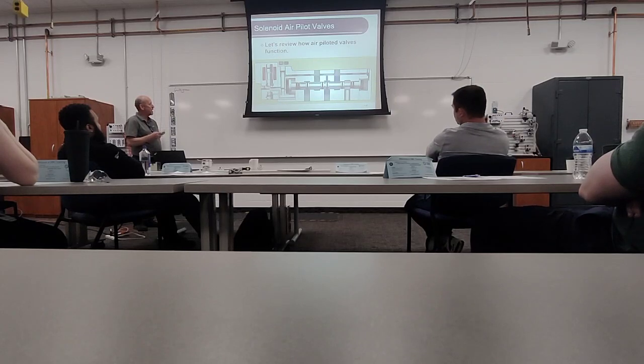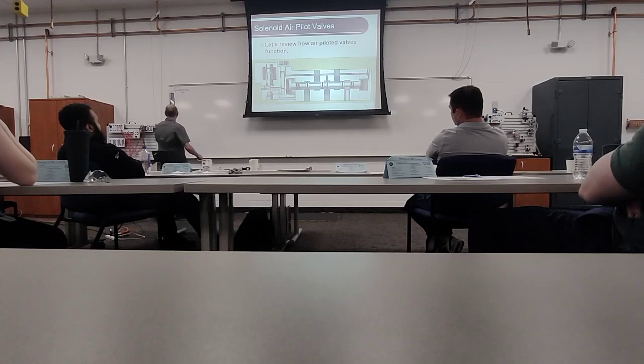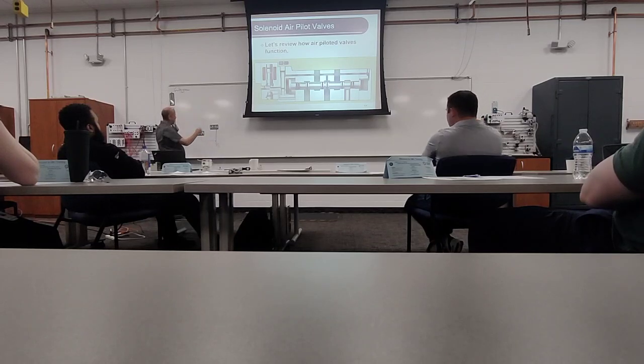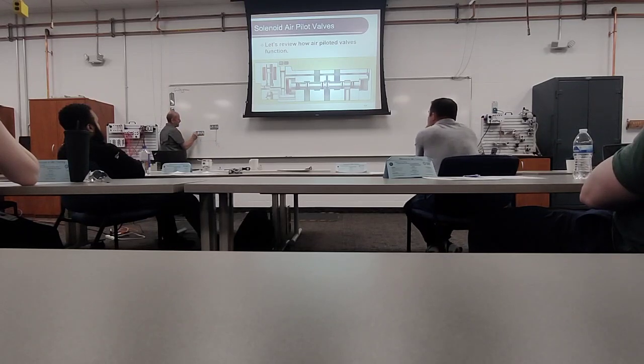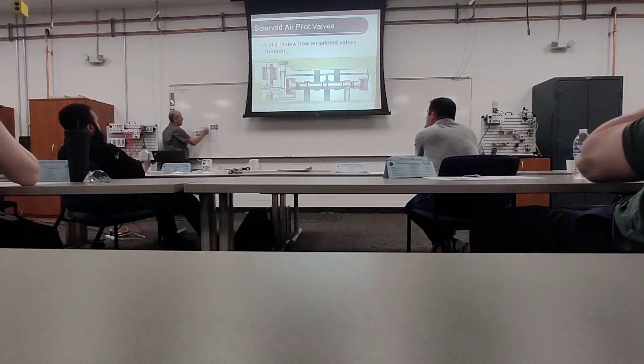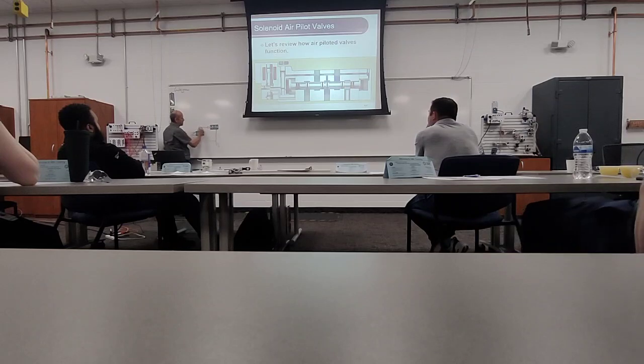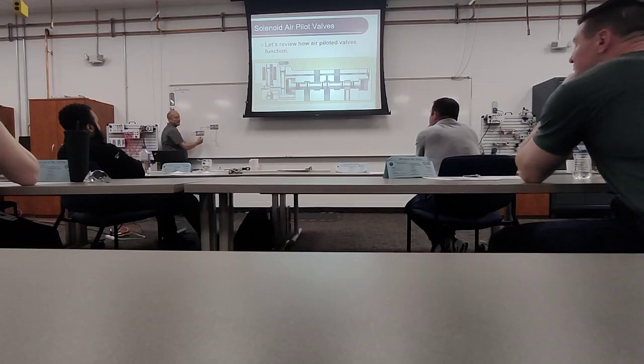This is the override, and then this is your solenoid valve. A solenoid valve is actually a 3-port valve. So what you've actually got in there, in this case, are 2 valves. You are sharing a common P port. We're tapping off the P port, right, for both of these. So we're tapping off the P port and bringing that over here. And then this is electrically operated. It uses very little electrical. And then this is my pilot air. So this is my pilot valve. And then this is my actual valve.